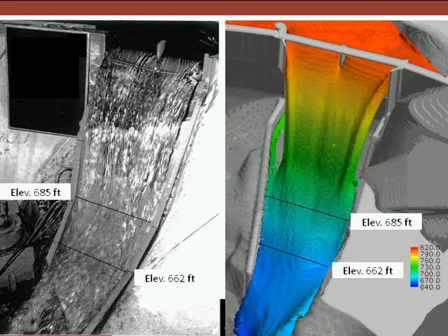For validation, this is one where we went back to the physical model study that we did back in the late 1950s. And what we can look at here, at least qualitatively, I'll try to use the pointer again here on the black and white picture, is how the water bulks up here at the contraction, and if we get something very similar that occurs in the numeric model. We can also look and see where it strikes the catch chute down in this area here. We notice that we get basically the same spot where it strikes in the physical model. So at least qualitatively, the CFD seems to be doing a good job on this particular project.